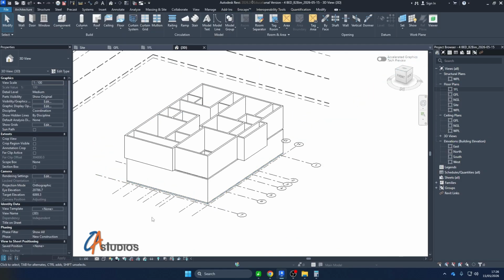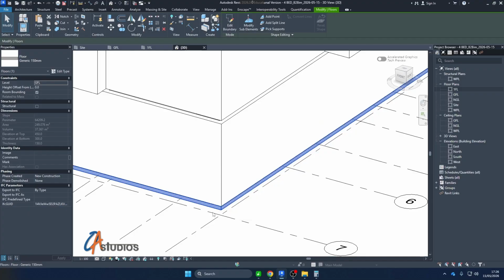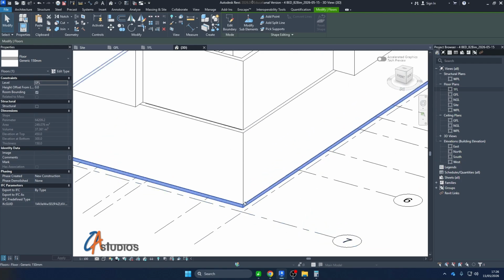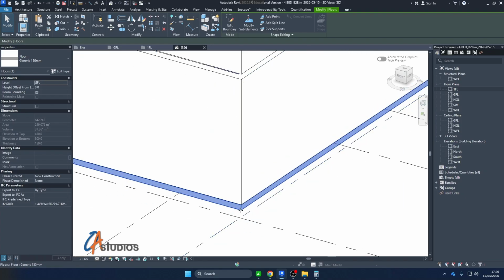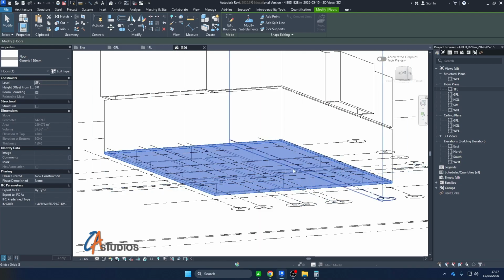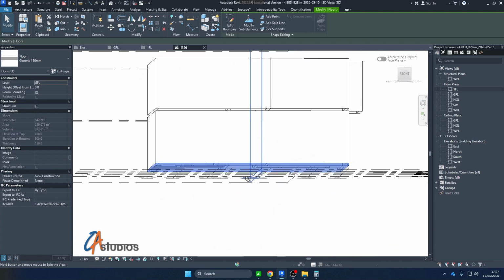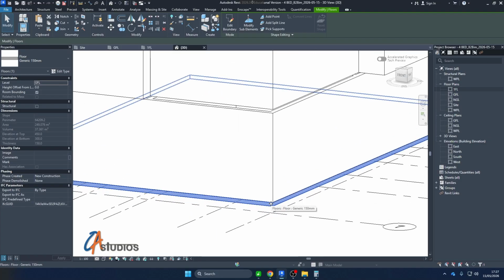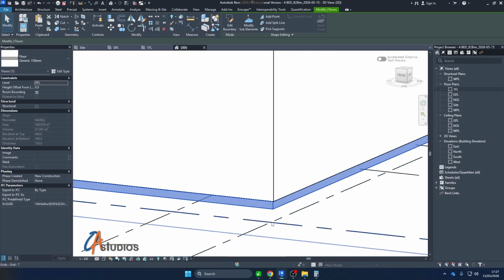Now for basic modeling, where you're not doing so much scheduling per se, what I like to do, instead of keeping this floor, which ideally for construction documentation has to be 150, so that I don't waste time modeling the walls going down to the foundation, is to make this floor the entire height of the space between the natural ground and the ground floor.